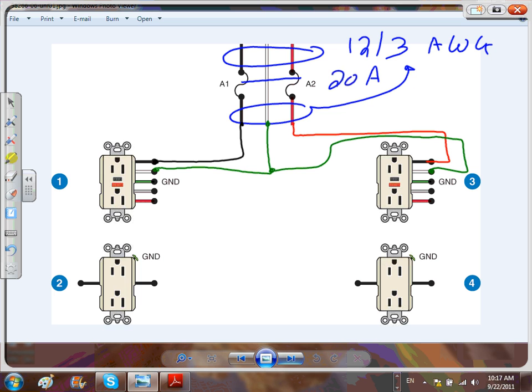my, granted, is this the load side or the line side? It doesn't say, so I'm going to assume, yeah, let's assume it's the line side. I grabbed the power, the shared neutral. Can you guys see the shared neutral? And I brought my phase. So this one is circuit 1, this one is circuit 2, and it's a multi-wire branch circuit. So this has to be a multi-wire branch circuit tied together. Questions about that?